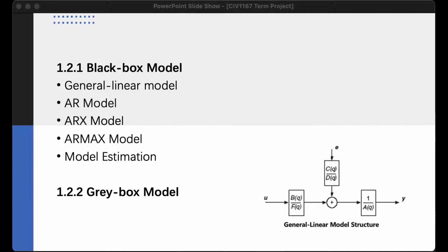For example, a wind gust affecting an aircraft is a dominating disturbance early in the process. The ARMAX model has more flexibility in the handling of disturbance modeling than the ARX model.